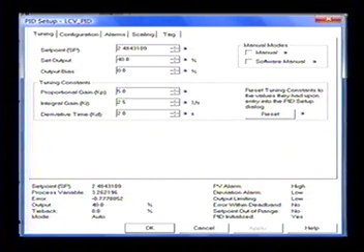Let's say that value is 10. At 10, this valve opens and closes. It modulates, right? It's cycling. Cut the value to 5. Just cut 10 divided by 2 becomes 5. Then take your integral and add half of the proportional gain. And if you do that, you'll find out that your process usually tunes at that point.